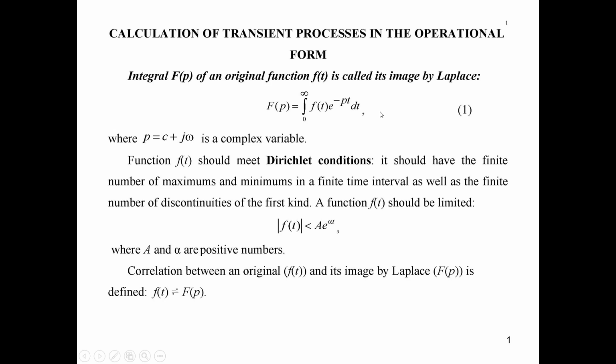just the argument of the Laplace transformation function. And here p is presented as a complex value. It's c plus j omega. And you see how this p, this variable, differs from just the application of phasors at presentation of currents and voltages changing by sinusoidal law with the help of a complex number. It will be just j omega.